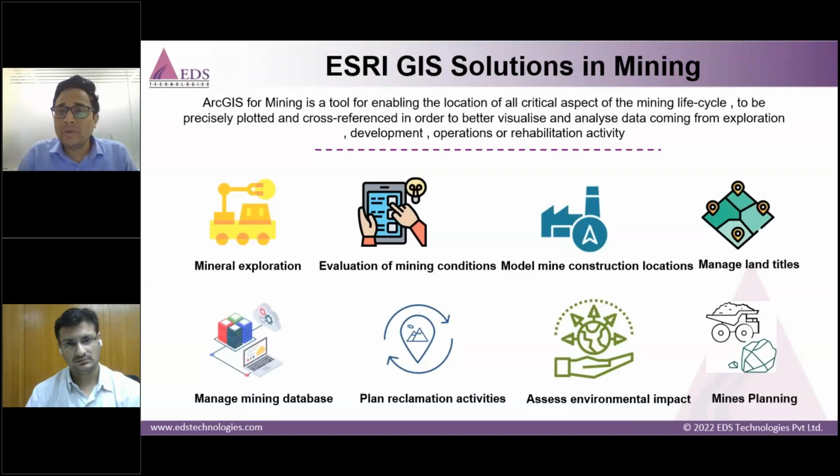So we can open PDF data in the software. We can georeference those data, cross-reference those data. The meaning of georeferencing is we can provide the exact latitude, longitude of each aspect, each point of that map. Once that map is georeferenced, we can easily trace all the information within the topo sheets as per our requirement.